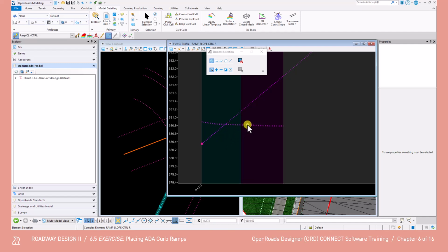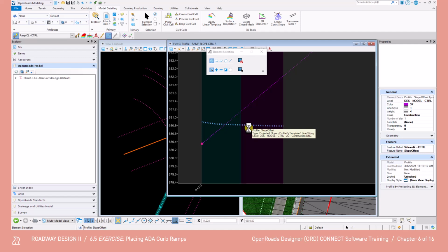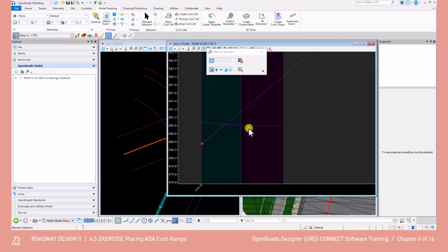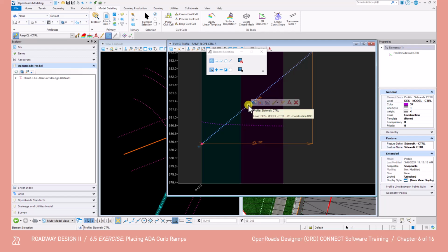So here we have the arced line. This is the base sidewalk profile from the intersection civil cell. The pink dot is the intersection of the lowered ramp right line. The line that is extending up is a slope control line where the slope of the ramp is controlled. There is a third line that uses the intersection of the arced sidewalks line and the controlling line to determine